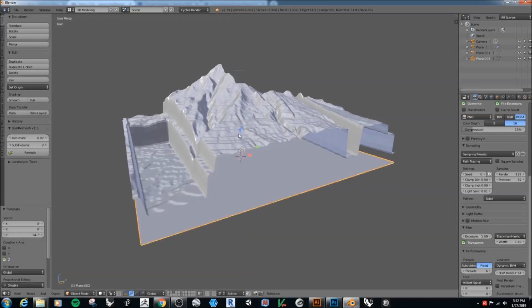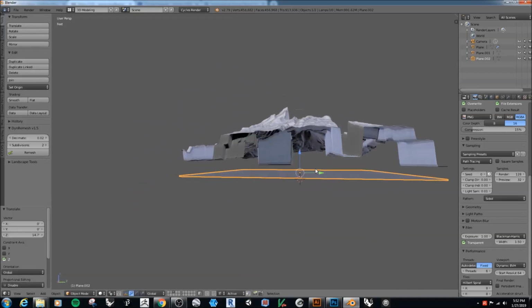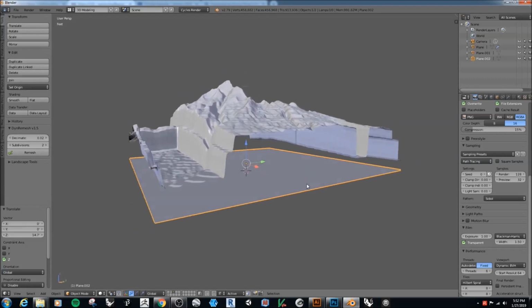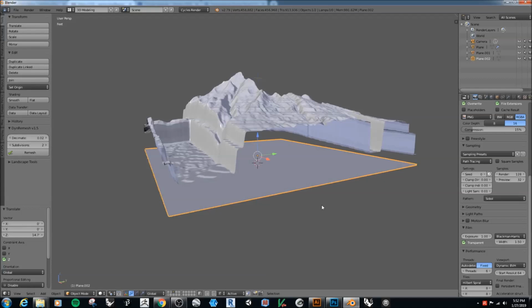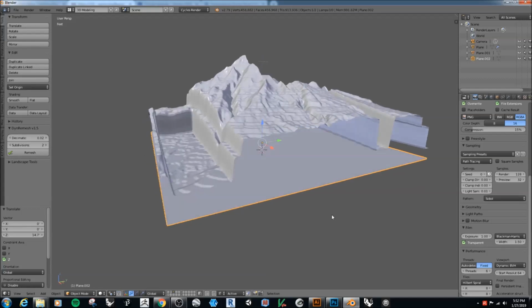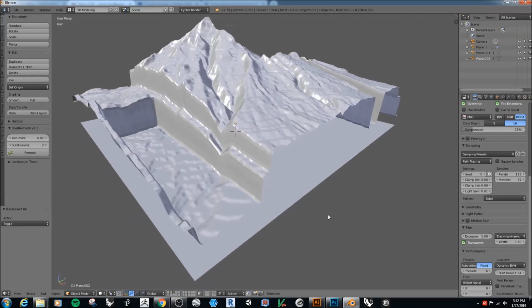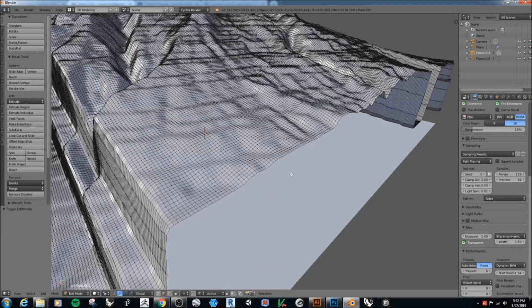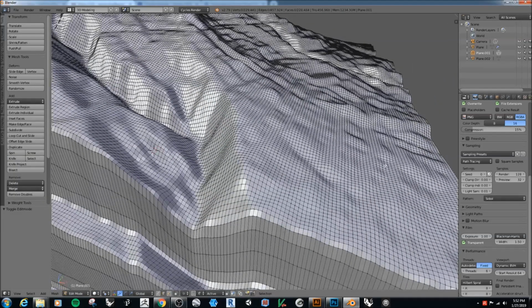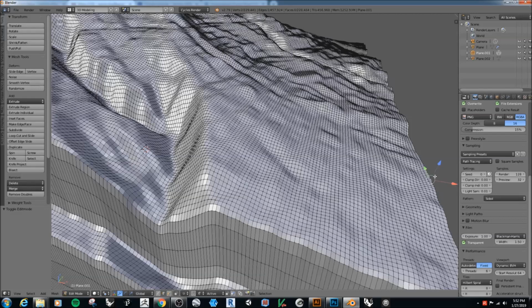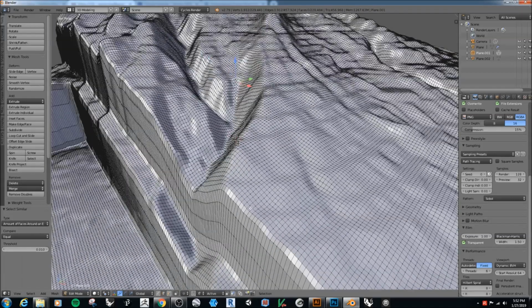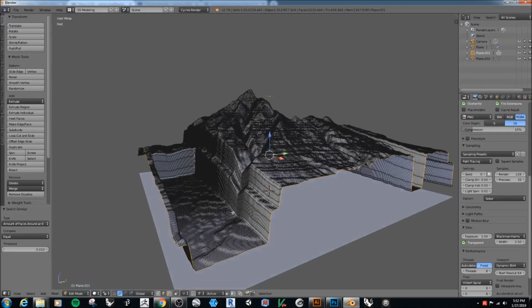So then we set this to where we want it, and again we're in scale, so we have an idea about how big this is. So I'm just going to do it there for now. And so because it's all gridded and mesh, we know that everything aligns. So now let's go ahead and pick this guy. Go back to edit mode and make sure we're on the edge selection. And we'll do that same thing where we select one, select similar amount of faces around an edge. And we should be able to cleanly extrude it.